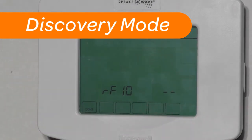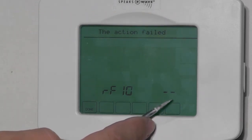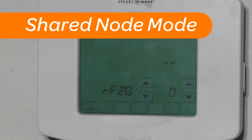If the DLC is working properly, the 2 dashes, once the thermostat is associated with the DLC, will change to a 2-digit number. When the thermostat is discovered, there is another option called RF20. This is called the Shared Node Mode and is available when there are multiple thermostats within the home.